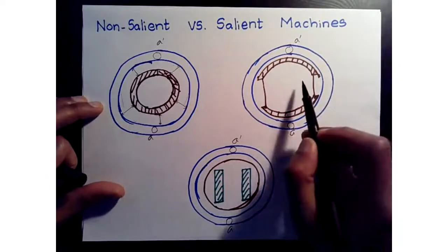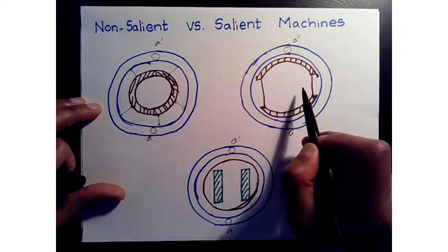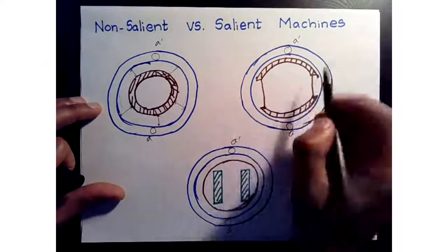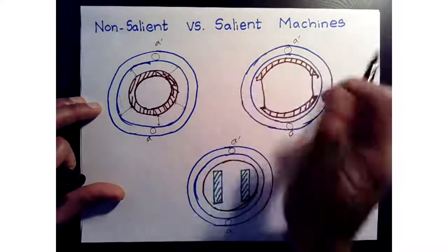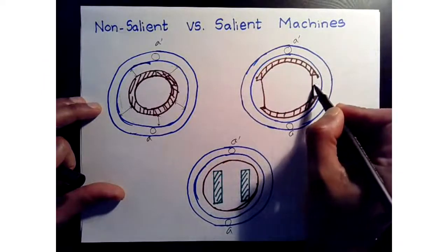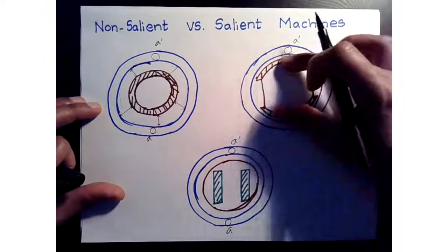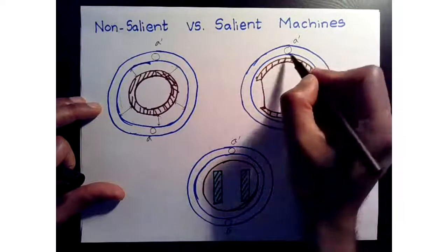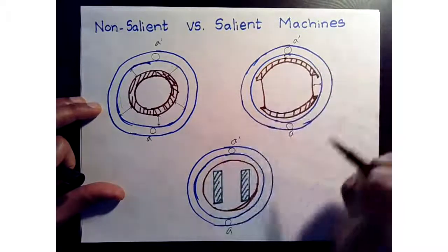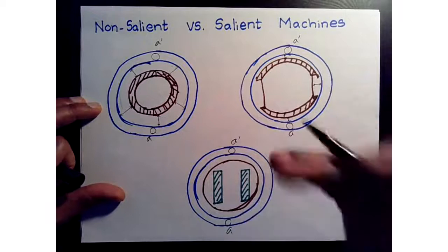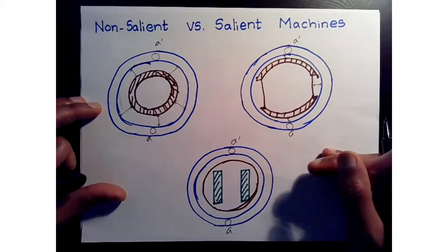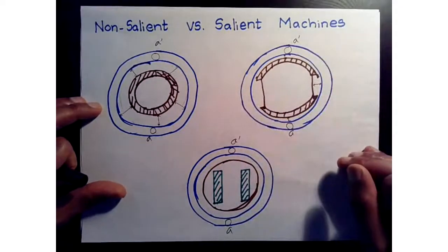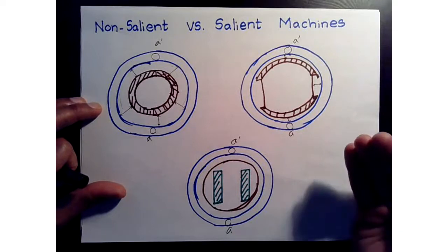However, when we go into this motor structure, we can see that depending on how the rotor is aligned, if the rotor is aligned this way, the magnetic path has a lot more air gap. If the rotor rotates and aligns in the horizontal direction, now we will see this air gap, which is much, much smaller. So that will have an influence on the total reluctance the windings will see. Therefore, the inductance will change. So this we call saliency.